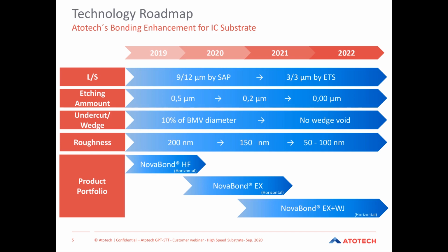So I mean that we move from the low frequency to the high frequency. What is a very important factor in this is the roughness of the conductor. That's the reason why the roughness of the conductor also needs to be lower and lower. Right now the allowed roughness is around 200, 300 nanometer, but in the future it will be down to only 100 nanometer, I mean lower than 100 nanometer. That means there's no roughness changing anymore. We just keep the surface original, and the process that we develop in the future will be no